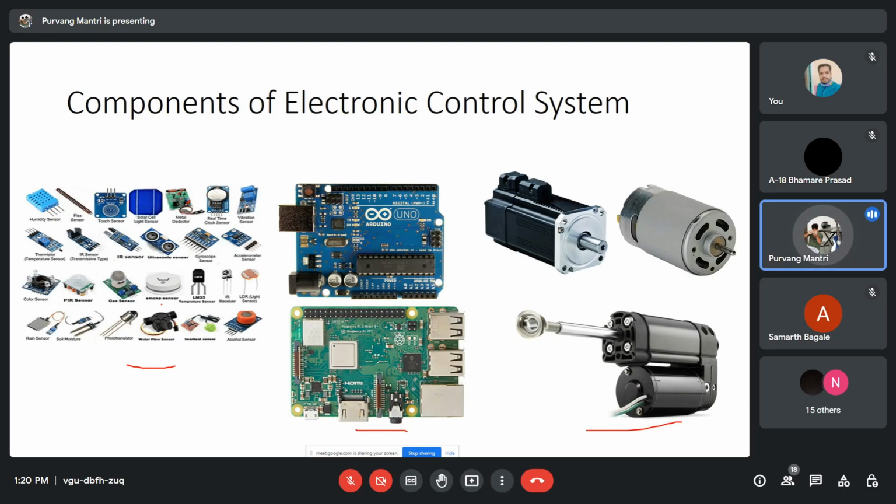So sensors have the ability to change their resistance for whatever quantity they are designed for. If the resistance is increasing and decreasing with time, and you want to measure that resistance, you need to have voltage applied to it. If this is a varying resistor and we are giving it 5 volts, and the output is getting reduced, we know that the resistance has increased.